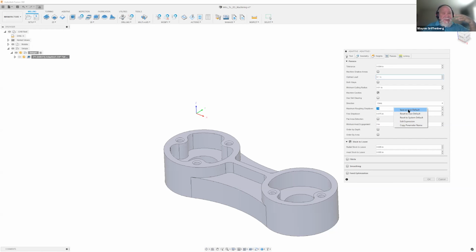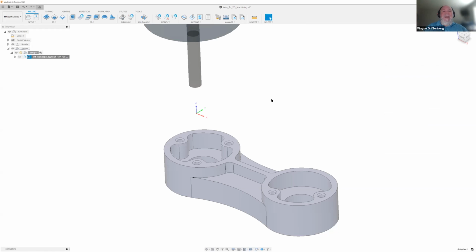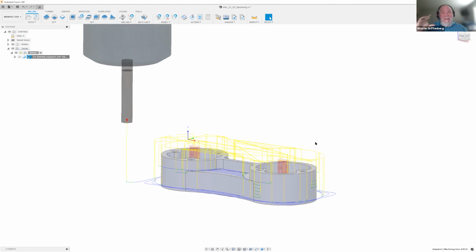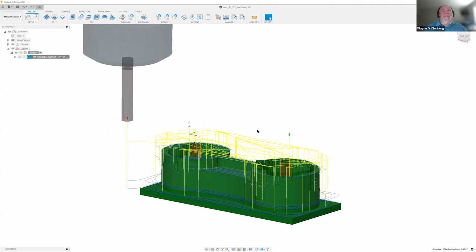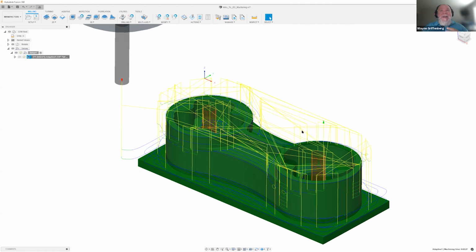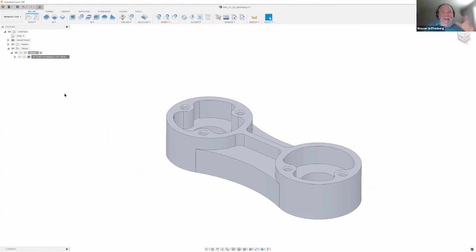And also, and maybe not in this webinar, but we can talk about toolpath templates. So now you can set up a series of toolpaths and save those out as a template that you can reapply to any part going forward. So I'm going to set that as my default, say OK, it reruns the toolpath, and now I won't have any collisions because I have a long enough flute length and long enough tool. So that I got to the part, I can see it looks pretty good. I might come back later on and finish this one up, but we just want to get some code out to the machine, right? So I just want to rough it.